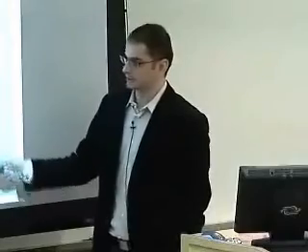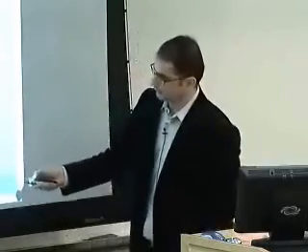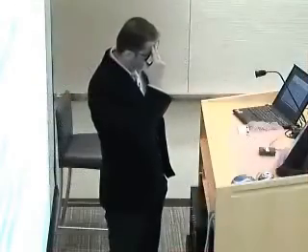What we need is basically a radio abstraction chip that on the one end can have an asynchronous interface for getting the data from the microprocessors, and on the other end can have a very high speed interface that can drive the 802.11 radio really fast and basically take advantage of its energy efficiency. So in that way, even the current radios and the current low power microcontrollers can be used together in an energy efficient way.